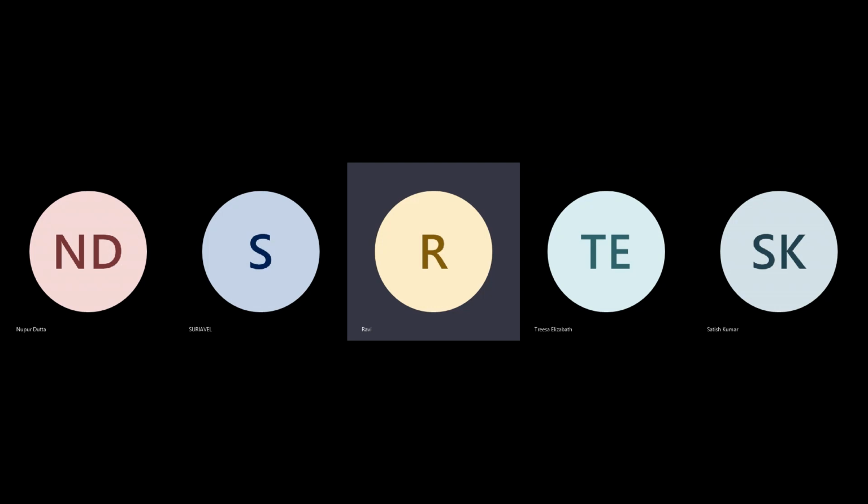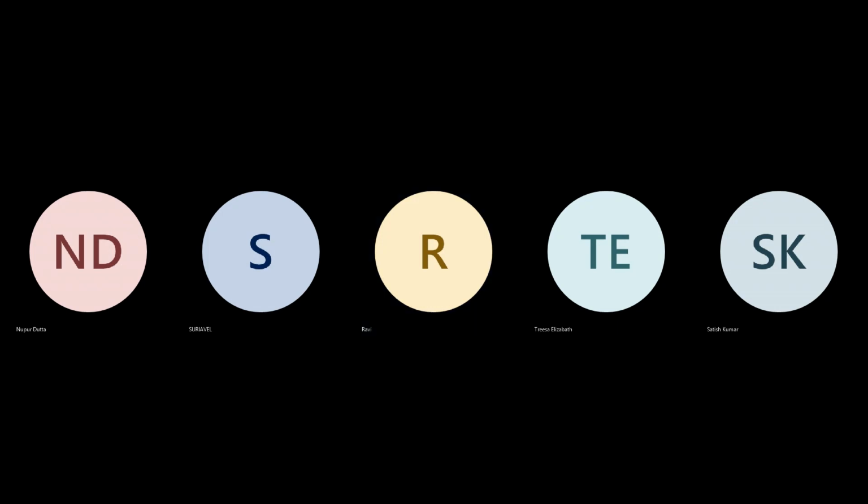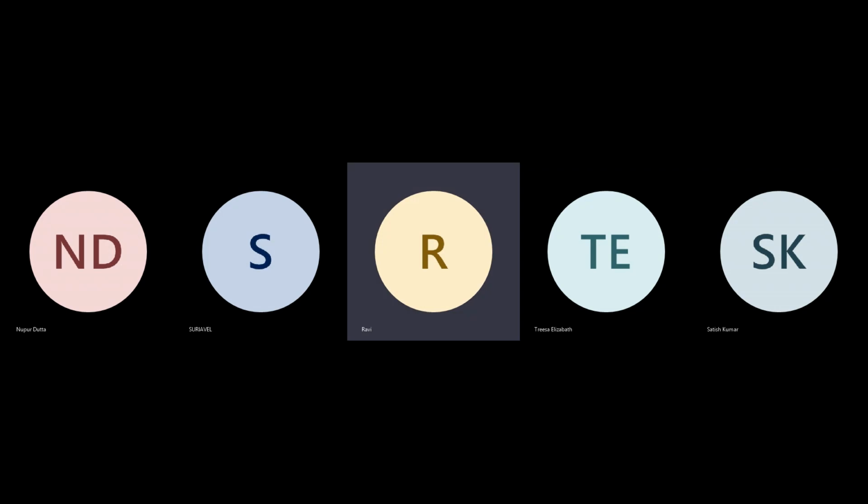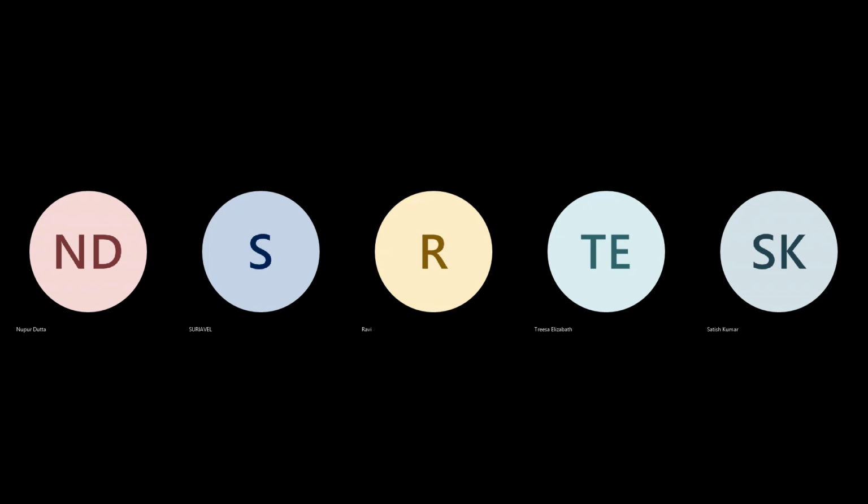Once the data comes, I'm going to start analyzing the global placement, the coarse placement, whether my modules are getting placed properly. If your modules are getting distributed, then there's a problem with your macro placement. You can stop, go back to macro placement, and create that second iteration quickly. You don't have to wait for 4 days. Second day, you will have another floor plan. Every day, keep running. So get that global placement, get that module placement reasonably good. That's the goal of initial coarse placement.